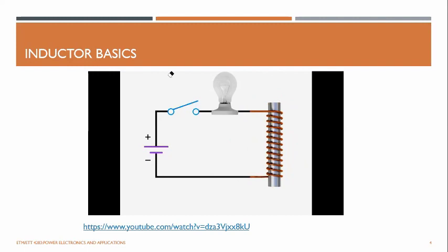And the other interesting thing is, like in the capacitor charging circuit, the capacitor voltage starts from 0. But in the inductor circuit, when you switch this on, the light bulb is off, which means the battery voltage VB goes directly across the inductor, because the inductor has the highest impedance initially since it doesn't have any flux. So it gradually creates this flux, and this VB goes down.